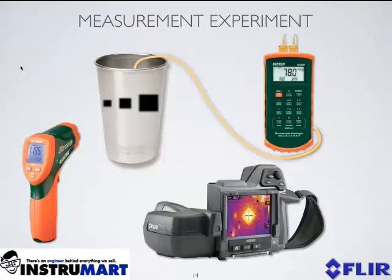Okay, now we're going to dive in and conduct an experiment. And the purpose of this experiment is to illustrate the different performance between these infrared sensing technologies. Now, the experiment that I've set up for today is a very simple one. I will place multiple pieces of black electrical tape that has a known emissivity value onto a shiny stainless steel cup. My target sizes, based upon the tape, will include 50 millimeter, 20 millimeter, 10 millimeter, 5 millimeter, and 2.5 millimeter square targets. I will fix a thermocouple inside the cup and fill the cup with hot water.